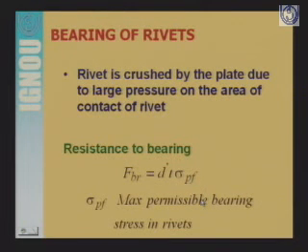Now let's talk about the bearing of rivets. Under the load, when the load is excessive, the rivet is crushed by the plate due to large pressure on the area of contact of the rivet and the plate.